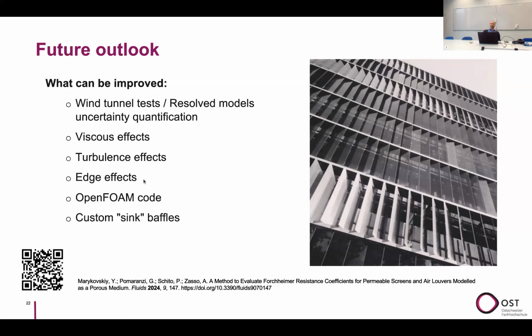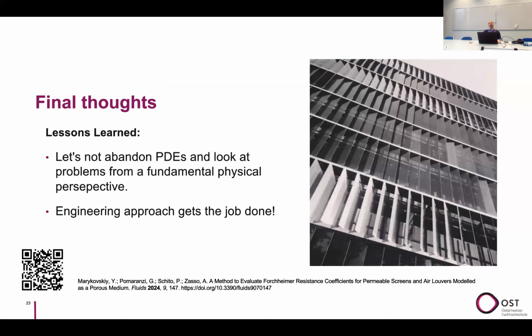In OpenFOAM, I found that there are some bugs related to numerical things. I don't think it's interesting to most of the people here. Another possibility is to have something called sync buffers. Again, it's something to do with modeling. So instead of modeling a volume or a part of a domain that has resistance, it's possible to introduce just a surface and then introduce custom resistance coefficients there.